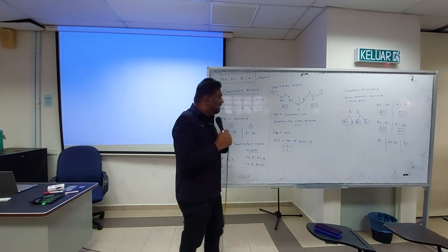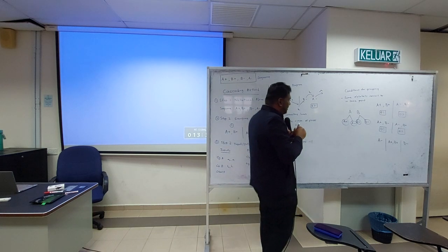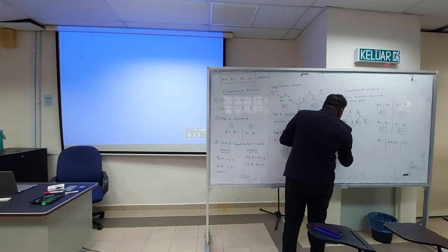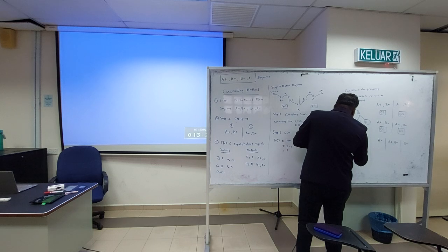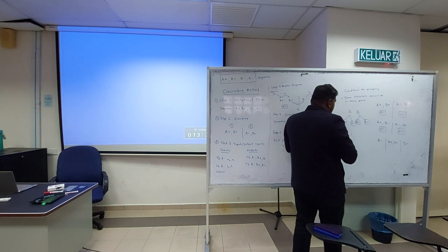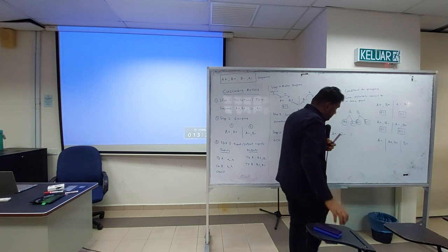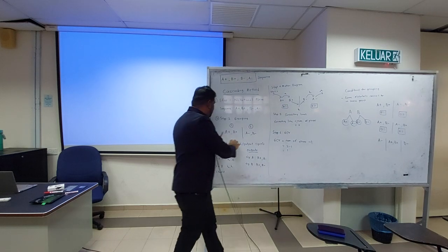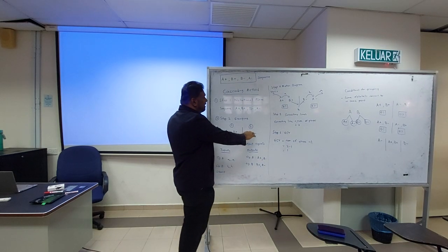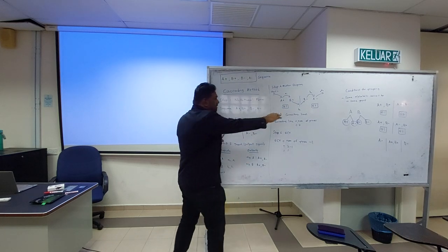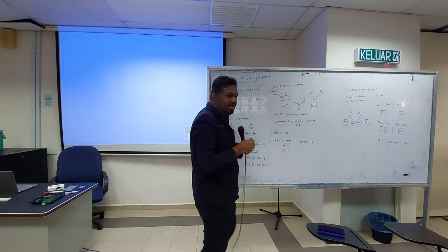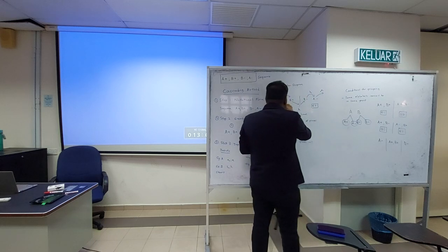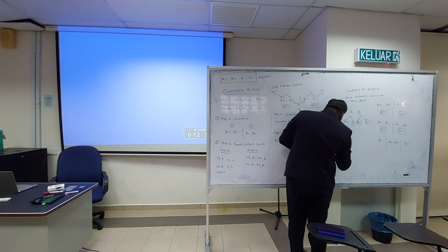Maybe you have a question. If I put A plus, B minus, suppose you use this, how will my motion diagram be? If this one, it follows the sequence, because the grouping and the sequence happen to be the same, so you just put one line. But what if I choose this grouping, A plus B minus, but the sequence is A plus B plus? Here, what will you do?